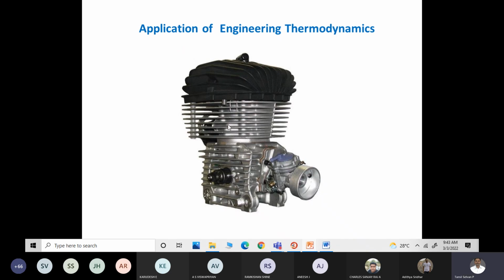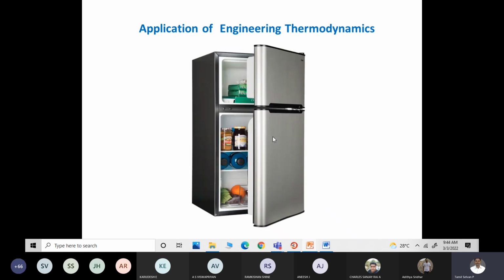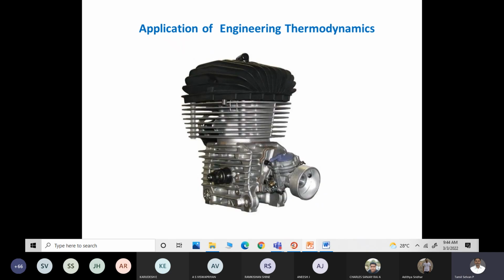And we will be having different types of fins. Circumferential fins will be there, so you can see at the top also you will be having fins, and along the circumference also we will be having the fins. Is it fine? Again, this is an example for heat transfer, where heat transfer occurs when the vehicle moves forward at a certain rate. Then we will be having forced convection. When the vehicle is stationary, then we will be having natural convection. Is it okay?